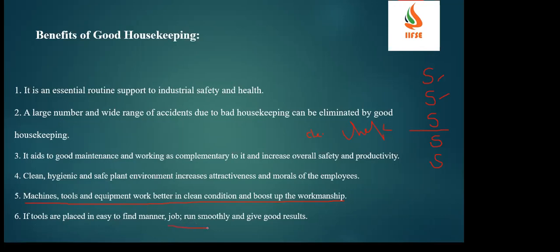So it also avoids the searching time. Here itself we have done sorting. Then here we have done set in order. I put all my tools in a proper way. So what will happen? I need not search. Immediately once my job comes, I'll go and pick my tool and finish the activity. So I can avoid the waste of time.